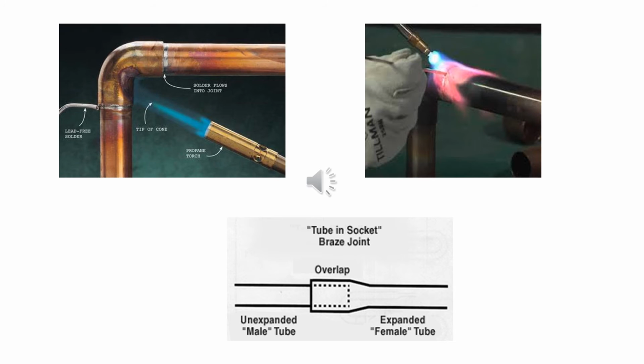As such, the filler metals for soldering and brazing copper and copper fittings must have melting temperatures below this temperature. Soldered joints depend on capillary action, drawing free-flowing molten solder into the gap between the fitting and the tube. Flux acts as a wetting agent and when properly applied permits uniform spreading of the molten solder over the surfaces to be joined.